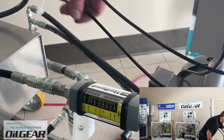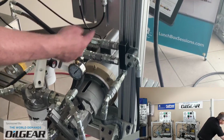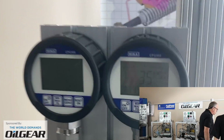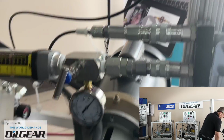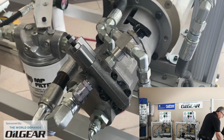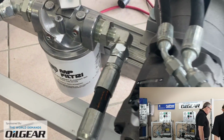We're measuring the pump's pressure on the outlet line with the digital gauge, and you might notice that we've got the load sense compensator on there. This is a DFR compensator if you're reading the data sheet for this style of pump.